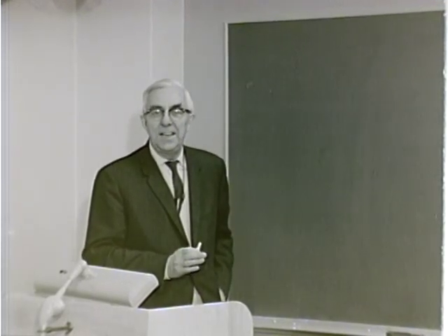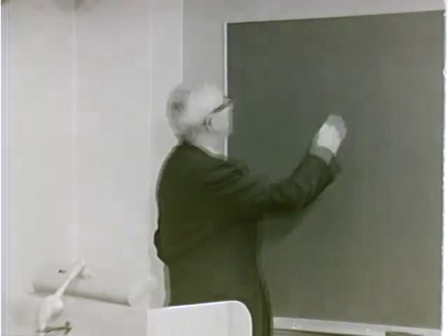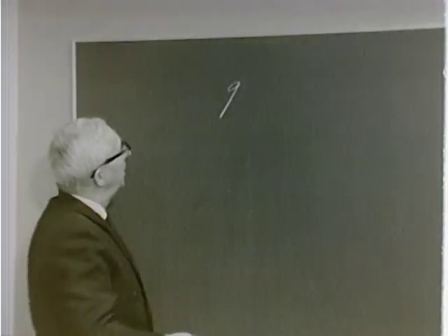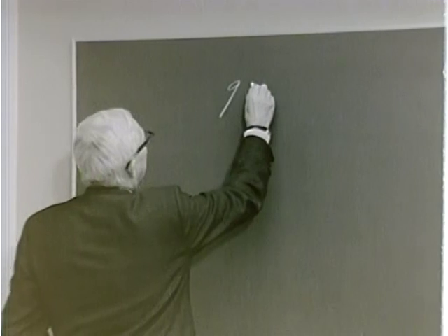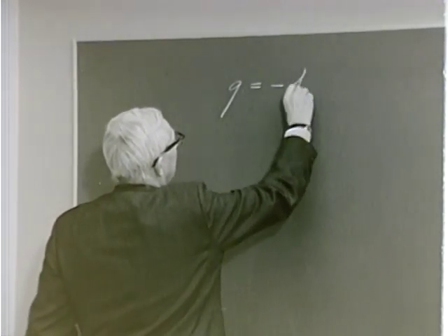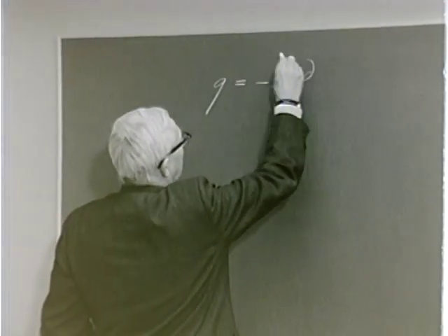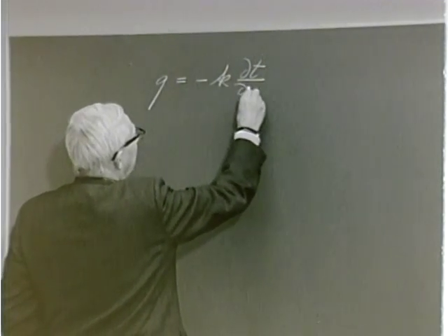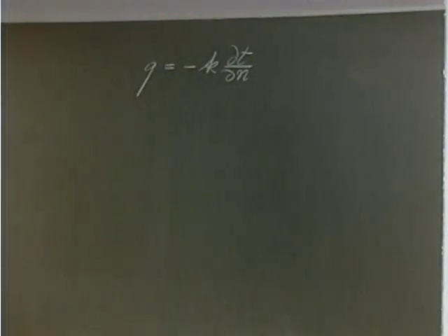In the last lecture, we came at the end to Fourier's equation, which we wrote in the following way: the heat flux per unit time and per unit area by conduction in some medium can be expressed in the following form: minus K, the thermal conductivity, times the temperature variation per unit length along a normal, or let's say along a heat flow line.